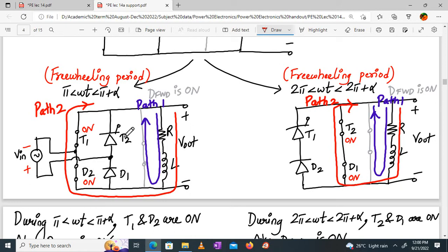I'll tell you, you should consider part number 2 for two reasons. First of all, ये जो T1, T2, D1, D2 है, इसके पूरा semi converter dependent है. If something happens to these devices, wrong, faulty, you should always protect them. इसलिए externally लगाया है, you connect a separate freewheeling diode. Second reason is, we are assuming that these are ideal devices.